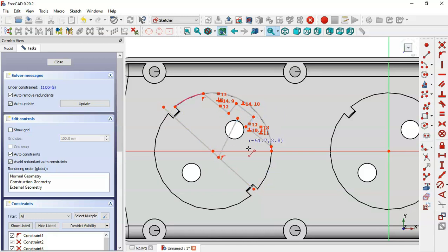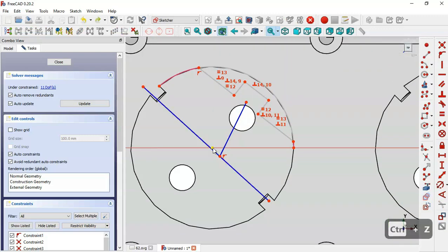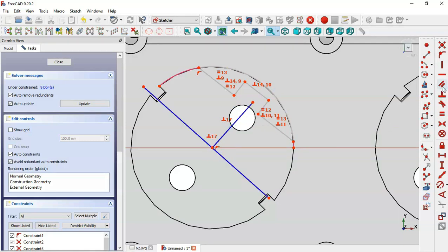Draw these two lines, and next here we select these two lines, and now in this icon here, okay, here we select this point and this line here and this constraint now, and now we set constant for these 2 points here, and we select this perpendicular constraint, and we set these two lines perpendicular, and now these two lines parallel, and here we set this merge constraint between these 3 points here.